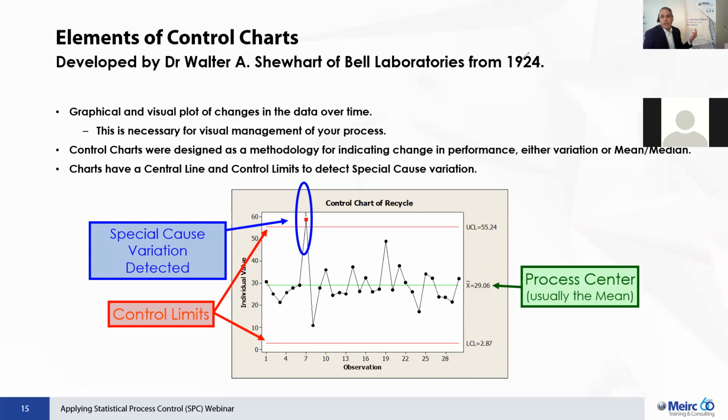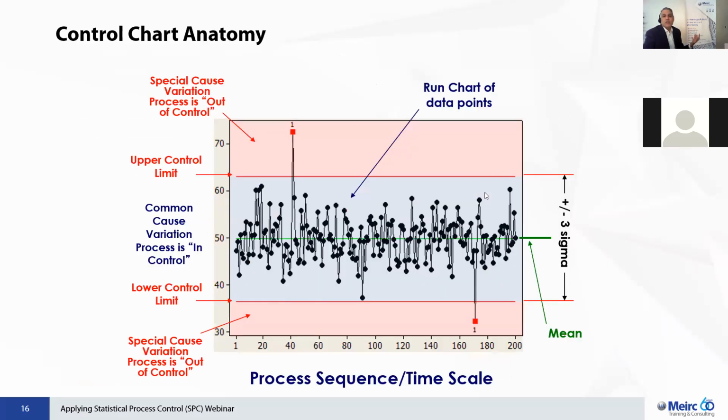So when we start thinking about this chart itself, we can see here the same chart. You can see that it is common to have variation between the different center lines. And as we said, it represents 3 sigma up, 3 sigma down, which captures 99.73% of the process performance. So as if we are saying, if your process is ranging around the center line and capturing 99.73% of that area, then your process is exhibiting what we call stable. That's the word that we use, stability.